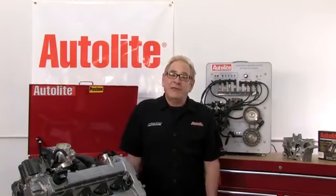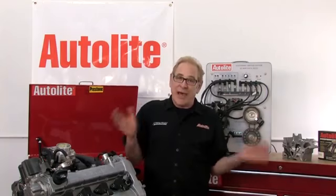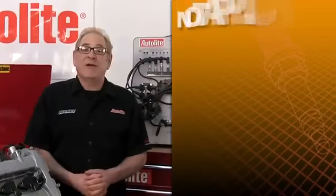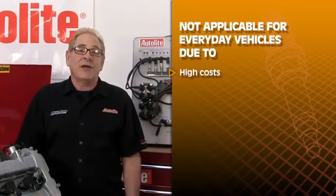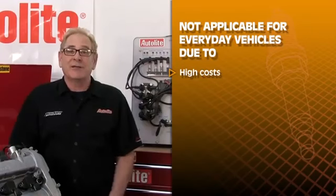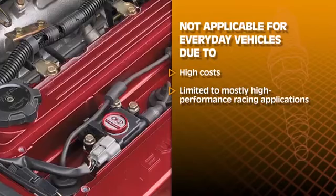So what application does a plasma ignition have in a modern automobile? In today's world, not much really. While it does have tangible benefits as far as the ability to ignite extremely lean mixtures, all the costs of the high voltage components, electronics, cabling, and spark igniters have limited this to mostly high performance racing applications.